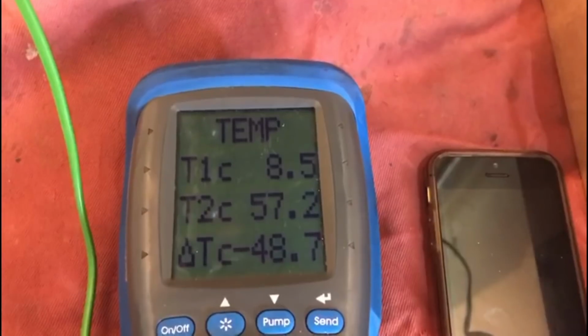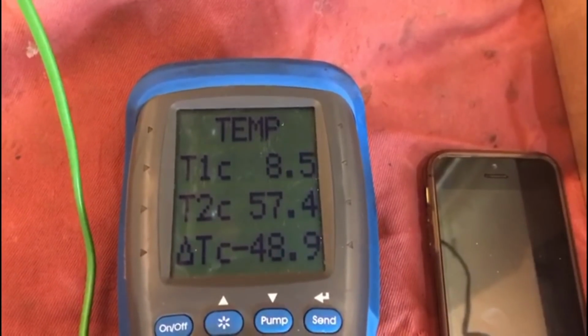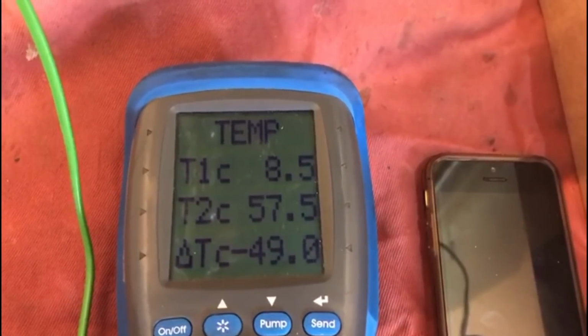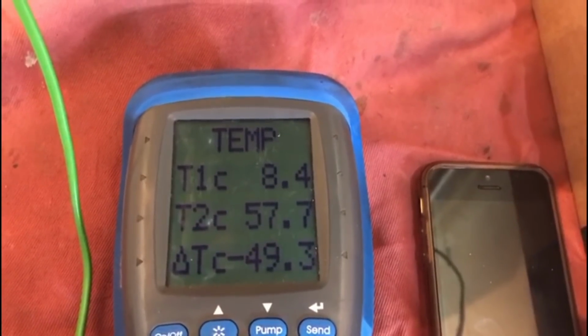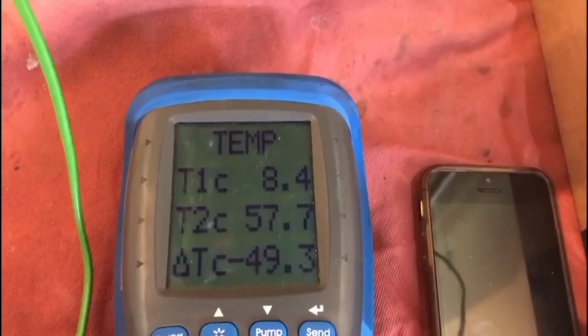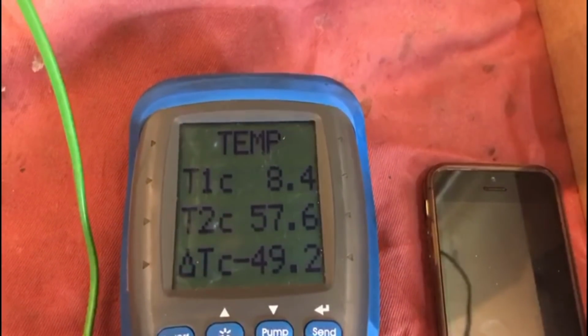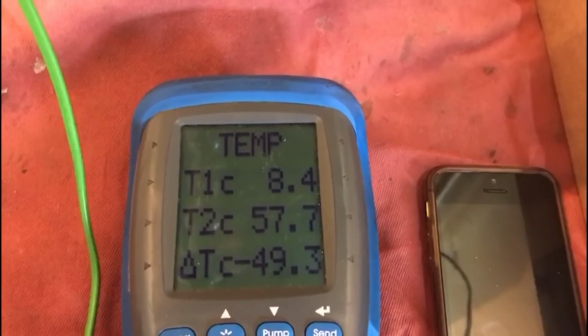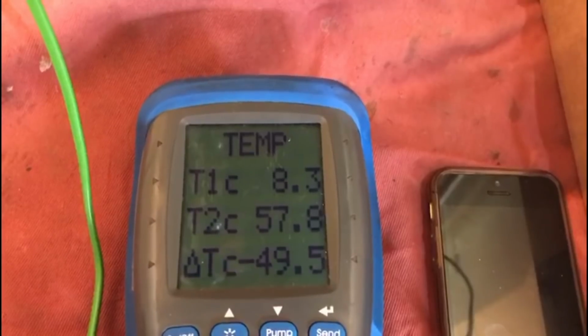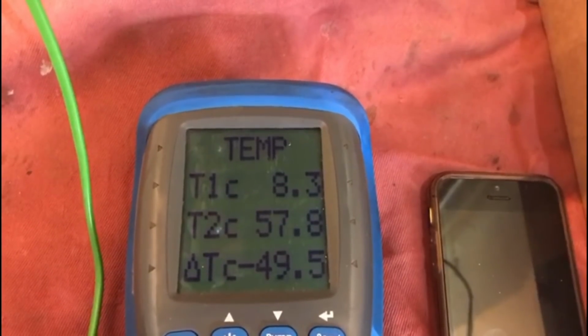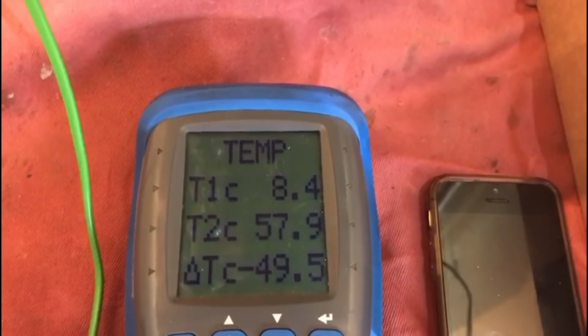But what you can tell from this is that it's actually achieved the 35 and exceeded the 35 degrees, and it's maintaining the temperature. That's a critical point we have to make, because a blocked plate heat exchanger will probably not even get to 35 degrees, and if it did get to 35 degrees, it wouldn't stay there very long.